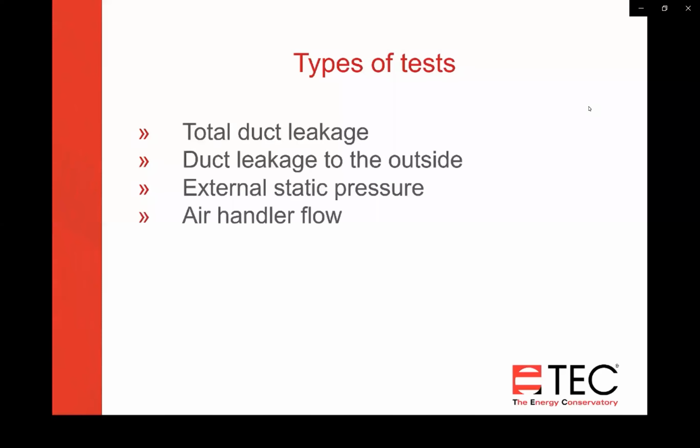Measuring air handler flow can help you diagnose comfort and airflow issues, and measuring airflow through registers. Are you getting enough BTUs to that room? If it's a room that is too cold or too hot, measuring the airflow to that room is a critical part of diagnosing the problems. Today, we're only going to be talking about the total duct leakage and duct leakage to outside. We won't be covering those other topics.